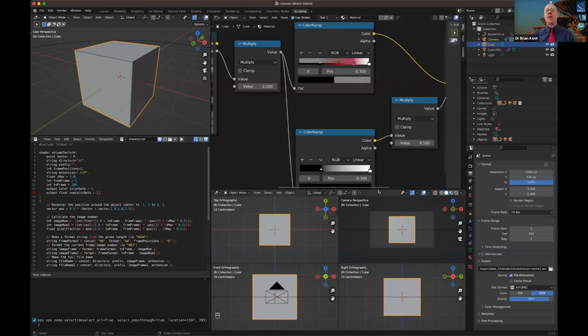So while my bottom color ramp is opaque, my top one here, you can see the checkerboard pattern in the background, is going to go from a white to kind of a red, a pinkish color, down to a red, a maroon, black, and then slowly go out in transparency. If you do any graphics work with Photoshop or graphics programs, you know that this is changing the alpha channel for your graphic. We're doing the same kind of thing here, but we're doing it for 3-dimensional volumetric elements, okay?